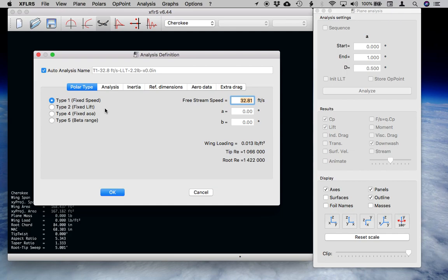You also want to maintain the same amount of lift. So as you're changing the angle of attack, you're also changing the velocity of your aircraft in order to maintain that lift equal to weight. You can also look at fixed angle of attack and then look at side slip cases where you're changing the beta.